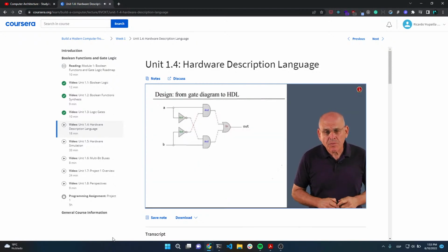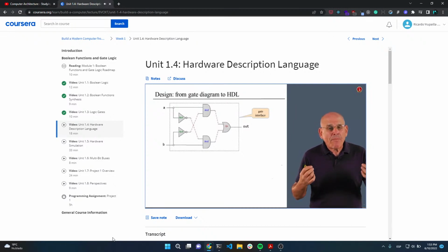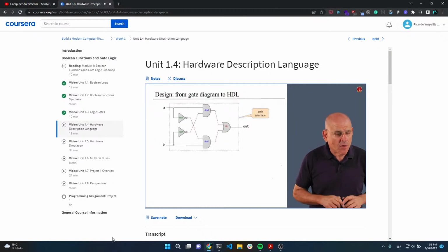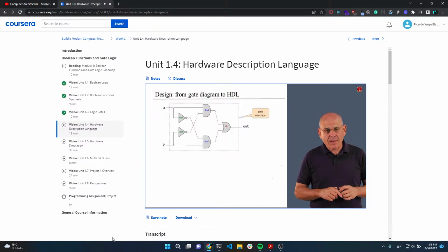So the first thing that we can do is draw the boundary of the chip diagram, or the gate diagram. So we use this dashed outline for this purpose, and what remains outside the boundary is the user's view of this gate. In other words, the gate interface. All the user knows is that he or she has a gate that has 2 inputs, A and B, an output called out, and altogether somehow this chip, as if by magic, delivers the XOR functionality. So we draw this diagram and this interface, and now we can delve more into the inner architecture.